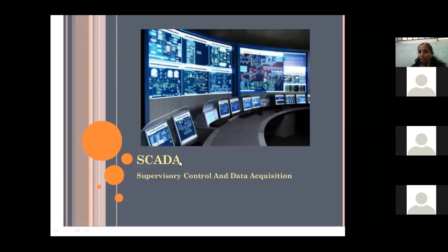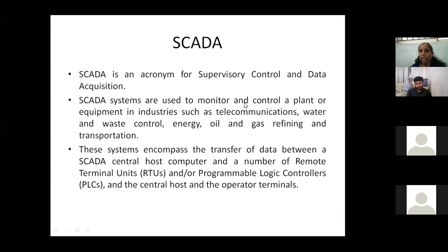Supervisory control in the sense that we may have 100 PLCs in the total manufacturing plant. For example, each individual CNC machine will be operated with a PLC. All these PLCs must be integrated together with the help of wide area networks. All these communication signals need to be given to a common station called a SCADA, where the SCADA is used to perform monitoring as well as control functions.